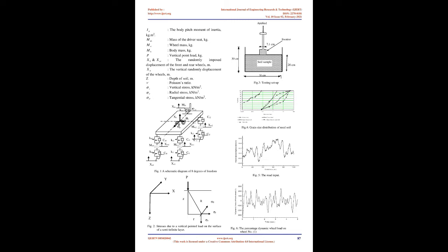The base was fixed to a steel rod of 5 cm in diameter and 20 cm in height, and soldered at the top of the rod to a circular plate of 10 cm diameter and 2.5 cm thick. This method ensures that the load over the footprint of 5.7 by 7.1 cm is spread. The load was measured with a 300 kN compression machine with a precision of 0.1 kN. Fig. 3 displays a complete configuration of the model.